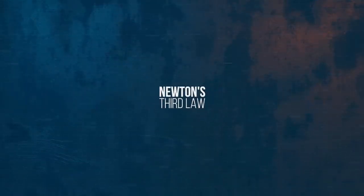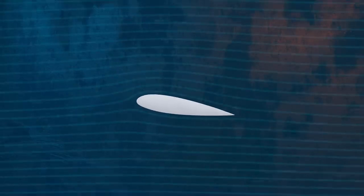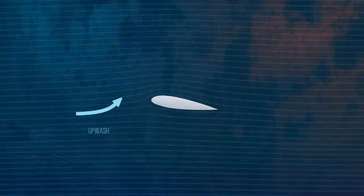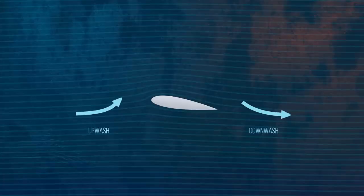These don't consider the velocity above and below the airfoil, but instead look more generally at the behavior of the fluid. If we look at a wider area, we can observe that the effect of an airfoil can be felt far beyond its immediate vicinity. Upstream of the airfoil, the flow is being swept upwards, which is called upwash, and downstream the flow is deflected downwards, which is called downwash. A very large volume of air is being displaced by the airfoil.